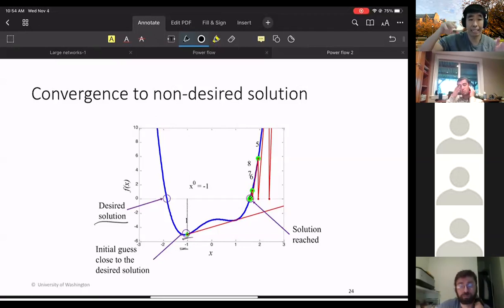The load will change, let's say, hour to hour. So let's say I'm solving power flow for 11 a.m. A reasonable thing is to say, okay, let's take the solution that I got for the 10 a.m. power flow equations and use that as the initial start for the 11 a.m. power flow equation. The load doesn't change drastically in 1 hour, maybe fairly similar. So maybe the last solution is a good guess for the next one.